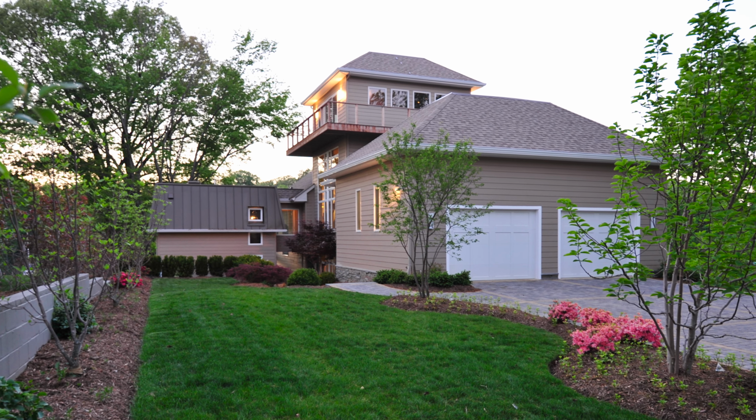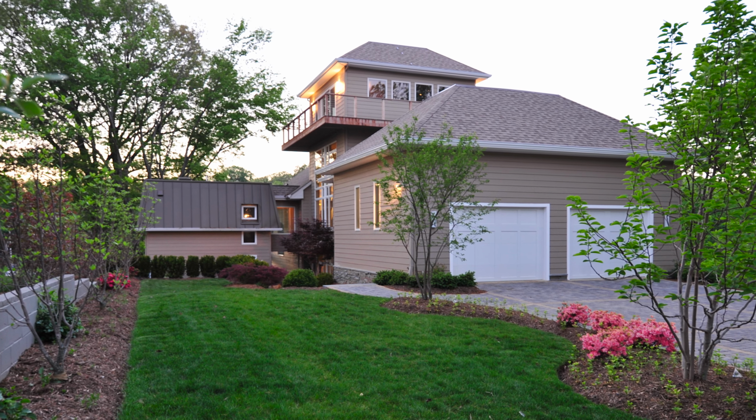Right, you have your elevation points, and then you also show the height. And usually on a residential project, the height is limited to 35 feet. But in this particular case, they allowed us to do the addition with a different height than the front, because most of the work was on the back side. Right, but a lot of people would count from here to there. It would be way more. Right. 35 feet would not be allowed.